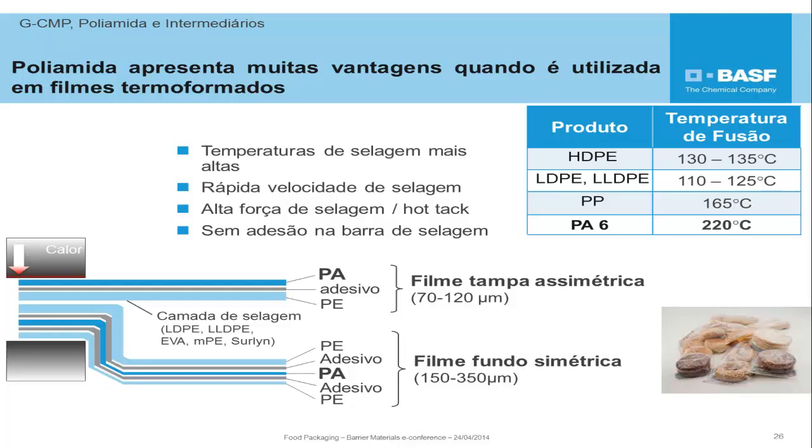Then, as plastic is not a good conductor of heat, the conventional system of sealing, the traditional system, presents a warm plate in the upper part and a cold mold, in general aluminum, on the bottom. The mold has a lining of rubber for container forming, but the warming to stretch and shape the material according to the mold, as well as for sealing the container, comes from the top plate with heating. Heat must pass through all the layers of plastic to deform the layers in contact with the mold and at the same time close the container.